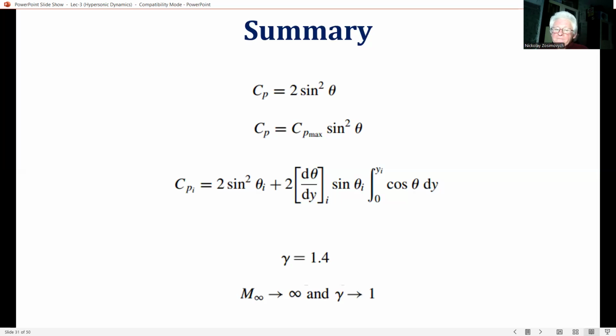For example, in the prediction of the pressure distribution over a hypersonic airplane, any cylindrical portion of the fuselage might be treated with the tangent cone method, whereas the wing might be better treated with the tangent wedge method.